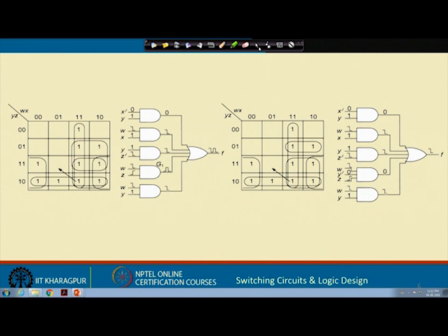But one thing I think you are appreciating now, that design of asynchronous circuits, making them hazard free is much more complicated. You will have to look at all possible scenarios for hazards, and then you will have to add additional gates. You see, I am looking at Karnaugh maps here, but think of larger functions, how to handle larger functions, very difficult, right. So, that is the trouble here.